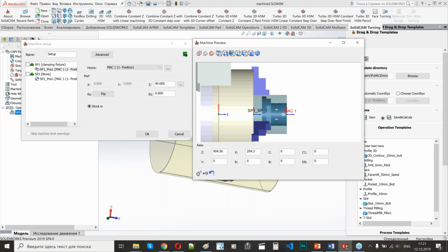This code does not look like ISO code. It is a set of internal CNC commands, but you can easily take a CNC template and just put figures directly from the SolidCAM setup window into this template, and the customer will get the possibility to double check the outputted code on the machine.